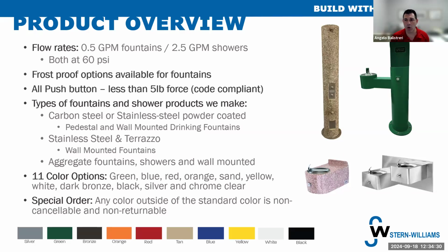If somebody were to hit one, nick one, and that powder coating chips and you expose that carbon steel, that is the piece that eventually starts to rust. And that's the piece that we're thinking about, the longevity side. If you're in a coastal region, maybe consider this.